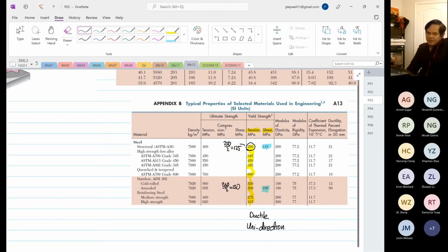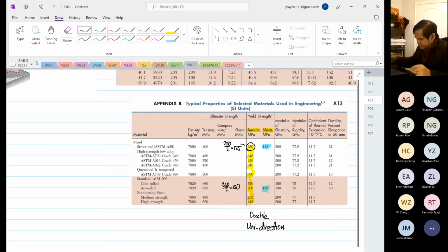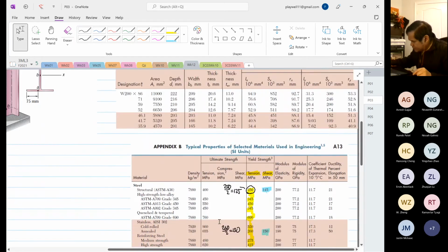You see that when your company were to test a material, they always go for what? Tensile, tensile. Why? The sample is easy to prepare, the equipment is more readily available. That's the only answer. Okay, you can design in twist, in shear, it costs you more. And the estimation of 130 and 150 is not so far away, so it's what? It's okay.